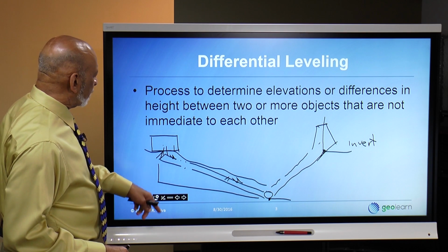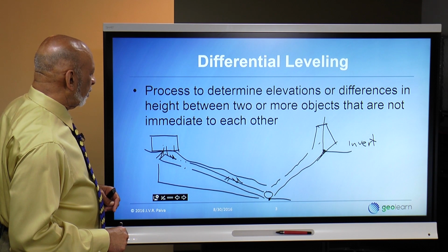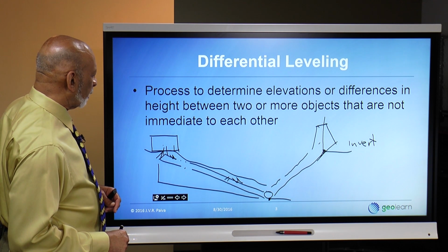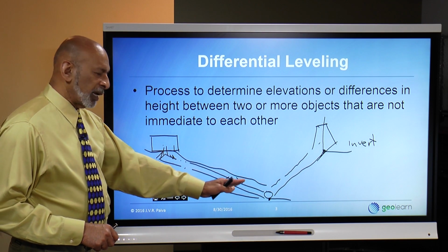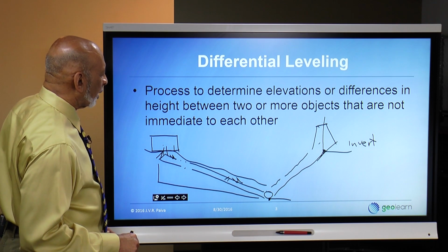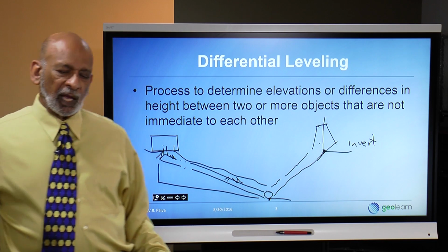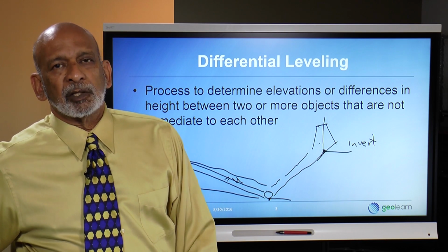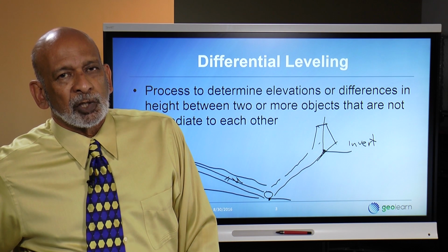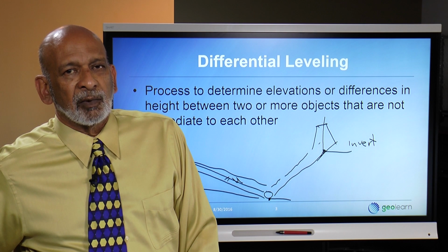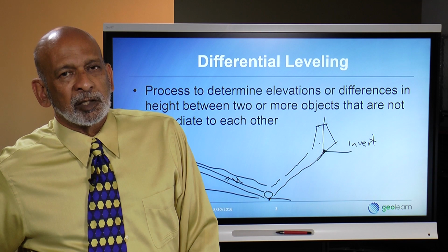And once you know that elevation, and you know the elevation of the top of the basement floor, you can now measure the horizontal distance from there to where the pipe exists in the street to calculate what that slope is, to determine if you have enough slope to be able to properly sewer the building. So this would be an extremely difficult problem to solve if you only had direct measurement tools to use. So you have to use other ways of making these measurements.